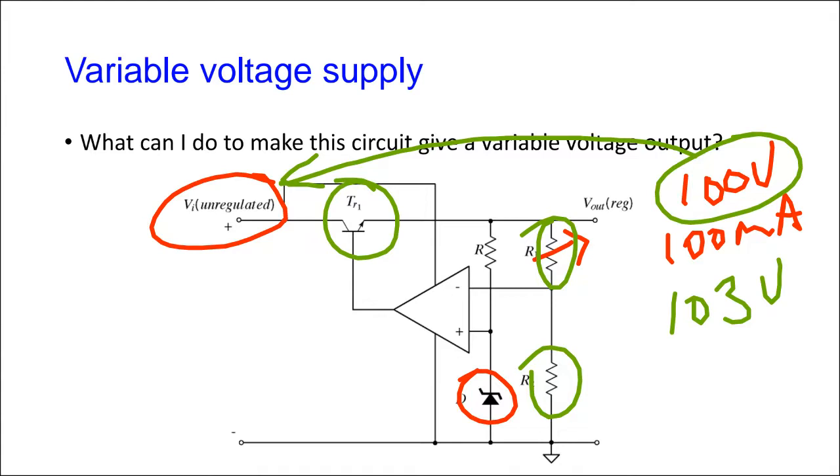All right, so let me see a current source. What's the question? Just now, let me put it back up on the chart here. Okay, so the question is whether a current source uses an IC instead of a Zener because the Zener forces a minimum, which is preferred. No, not quite. Just look at the circuit that we have here. We are biasing the Zener with a resistor.